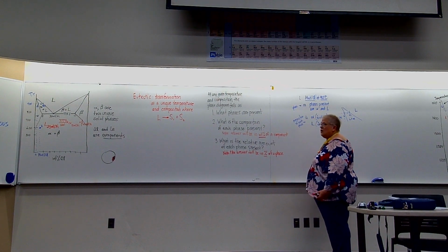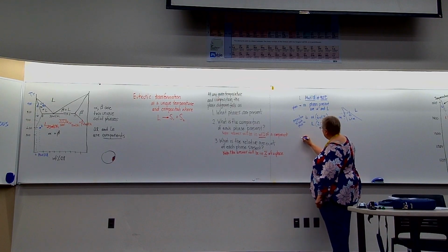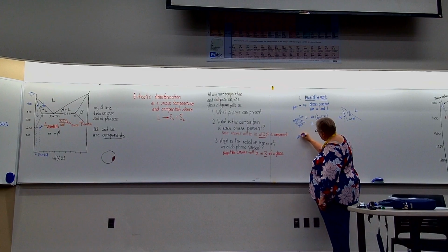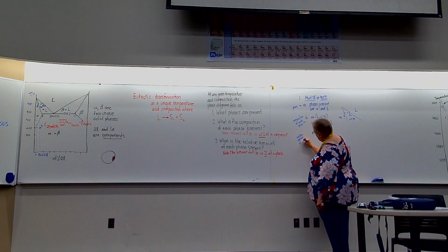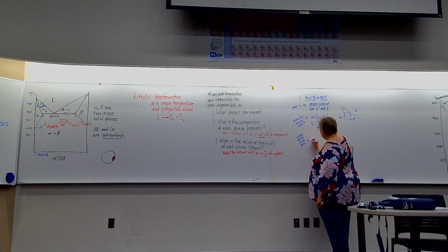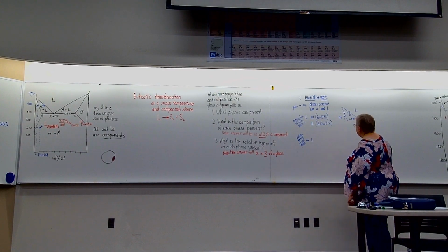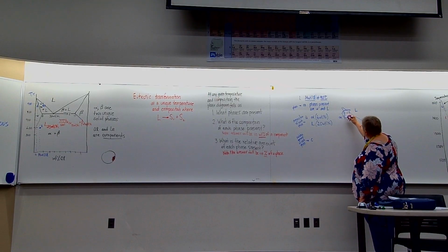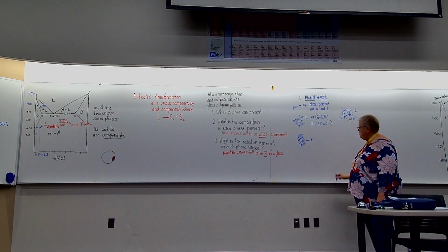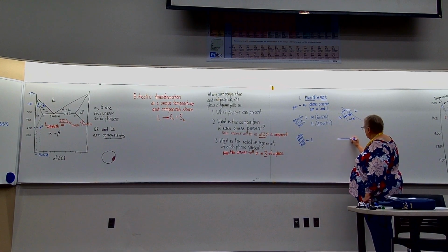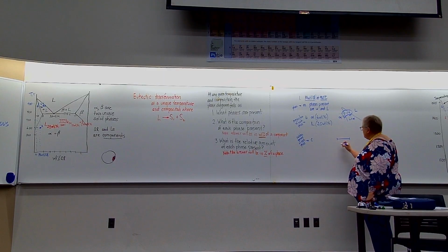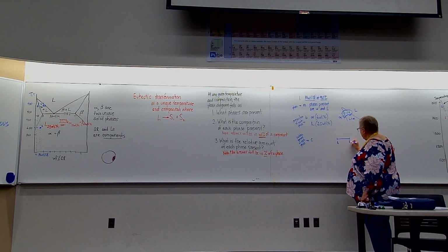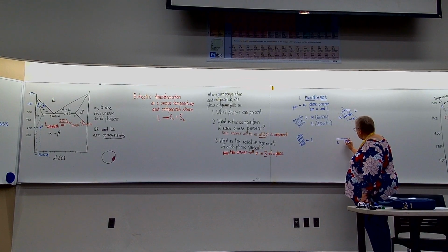Okay, the last question is, what's the relative amount of each phase? And to solve that, we need to take this part out and draw it. So I've got this length that goes from 6 to 20, and I'm at 14 there.